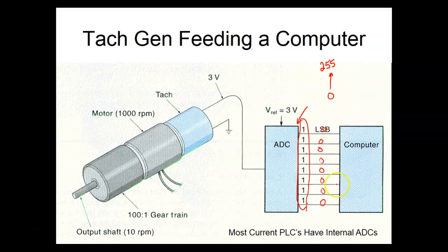Now, if you program these things with a programmable logic controller, this is the type of A to D converter that the PLC has in it. What it's going to do is give us a binary number that's equivalent to the speed. Then we would have to figure out a transfer function to figure out what number represents what speed. The MicroLogix 1100s that we have have a 10-bit A to D converter. So that means 2 to the 10th minus 1 would be 1023.